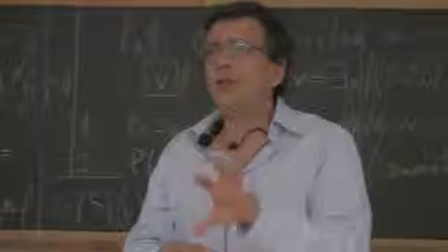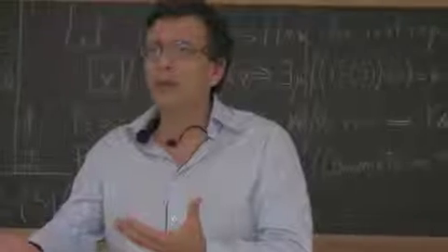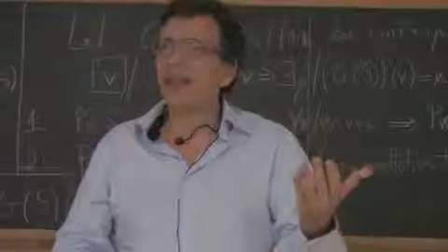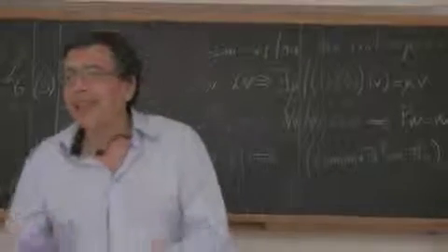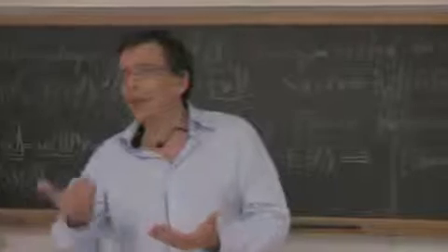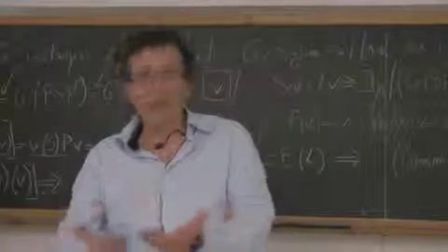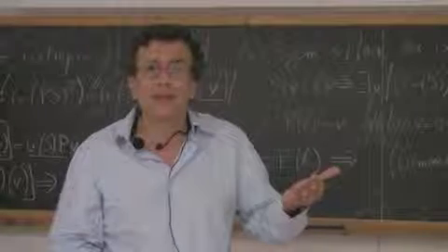If you have a constitutive equation mapping the deformation of a solid into Piola stress, you know that every eigenvector of deformation, if you have an isotropic material, is an eigenvector of stress.